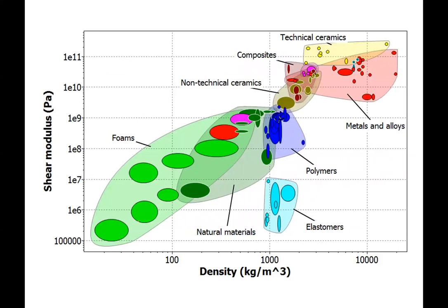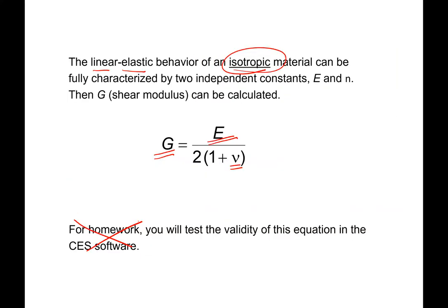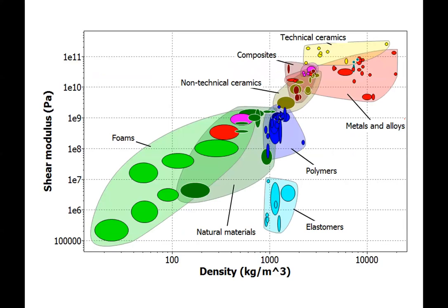So here's the value of the shear moduli. You'll see that they're not much different than the elastic moduli. You can see that from this equation. Let's say that nu was something like a third, right? Then this would be E over something like 2.6. And so we expect the shear moduli to be a factor of 2 or 3 different from the elastic modulus, but not orders of magnitude different. And so they're fairly similar. Again, the materials group very nicely when we plot this versus density.